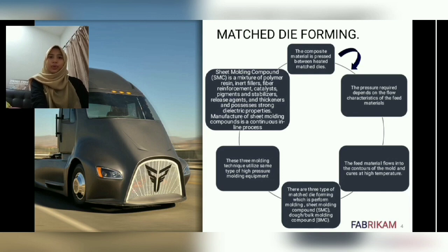The paste is spread uniformly onto the bottom film. Chopped glass fibers are randomly deposited into the paste. The top film is introduced and the sandwich is rolled into the predetermined thickness. The sheet is allowed to mature for 48 hours.